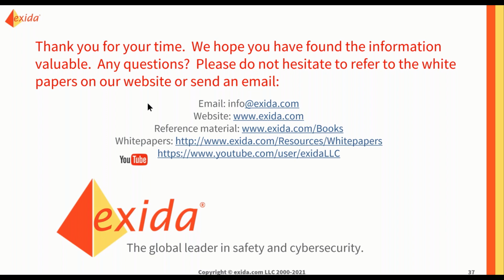How are SD failures relevant? They're only relevant. A safe, dangerous failure in a single, non-redundant system will cause a trip. In a redundant system, it may or may not, depending on what kind of redundancy you have. So the reason for having any safe failures, undetected or detected, is to calculate and predict the false trip rate.